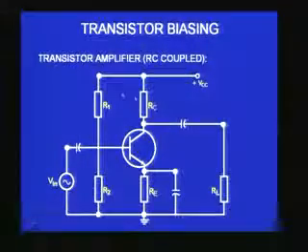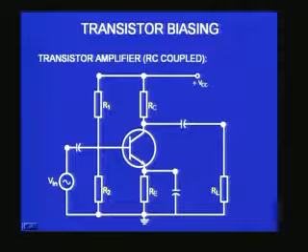Now let us move on to our transistor biasing circuit, which I now want to convert into an amplifier for amplifying AC signal, alternating signal. Immediately you can see, if I want to do that, the circuit that you see on the screen is one such amplifier, called an RC coupled common emitter amplifier. You can immediately recognize several of the resistors and the transistor in the configuration because we have just now seen that this is nothing but a voltage divider bias emitter biasing scheme. You have R1, R2 here, you have the RC, you have the RE, and you have the transistor.